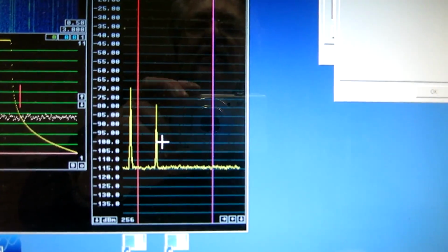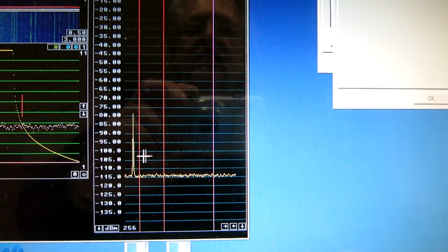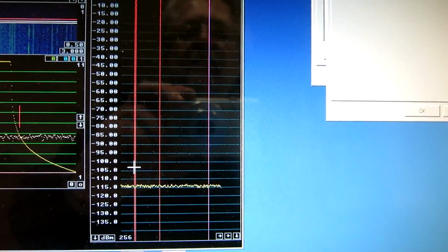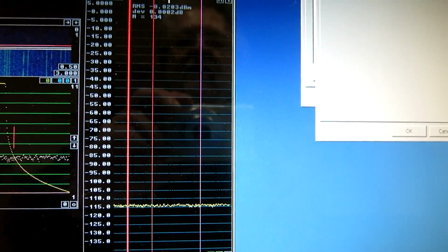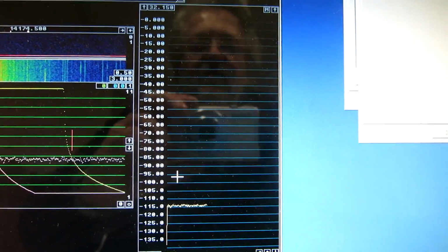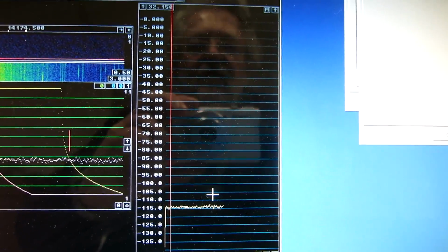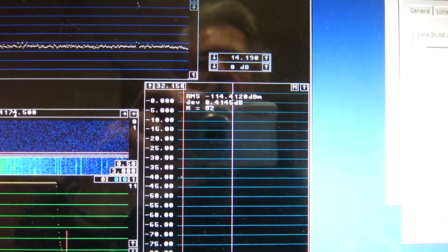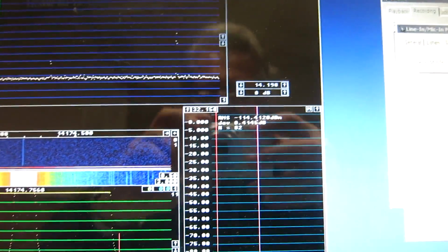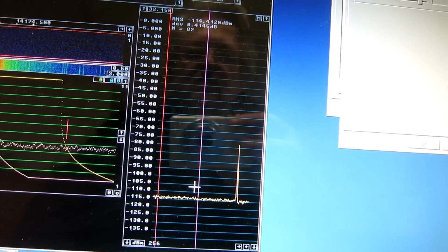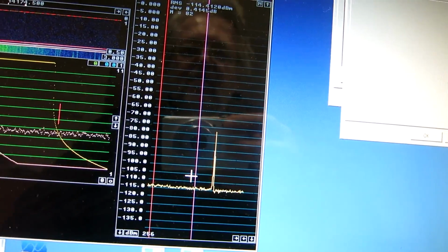The noise floor is, well, from here to here. This starts to be a little bit frustrating, but I want to make this sound card thing ready before going to find what is the bug in Linrad causing this. The noise floor is at minus 114.4. And that is with a strong signal present, and I switch it off. And reciprocal mixing is very small.